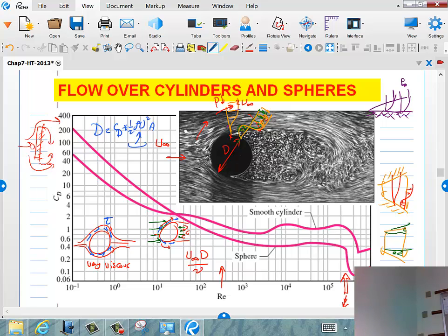So you can explain this with inertia, but later, if you take another fluid mechanics course after fluid one, you will study this in detail, and you will know where this point will actually exist. All right? The point where the flow will decide that I cannot keep going, I will just have to leave. Right? And it has to do really with the pressure in front of it. The pressure here will just be too high, and it will say, I cannot go this route. This is very high. I'll just go this way. So solving the pressure field will tell you exactly where this point is.